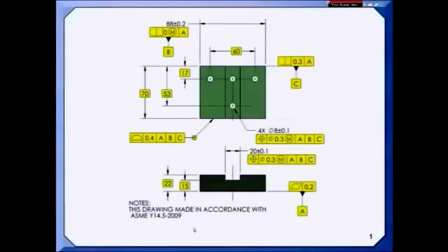This tip is about default tolerances that do not have one clear meaning. Referencing the Y14.5 standard invokes a whole lot of tolerances that keep our drawings quite simple. In a previous tip, I showed how this drawing and these geometric tolerances default or invoke all of these tolerances that you're seeing in blue. And they all have one clear meaning. In fact, you invoke all of these notes also, so I don't have to put them on the drawing.